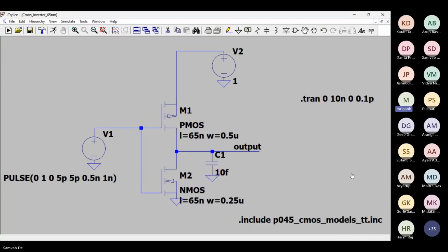And then when that charge is again shunted to ground when the NMOS turns on, that energy has gone from capacitor to ground. So overall charge CV has traveled from where? VDD to ground. Capacitor was just an intermediate halt.